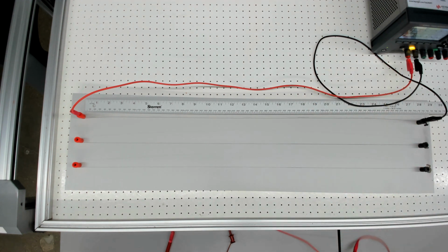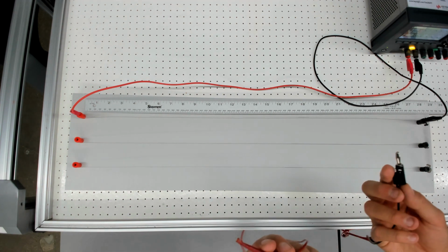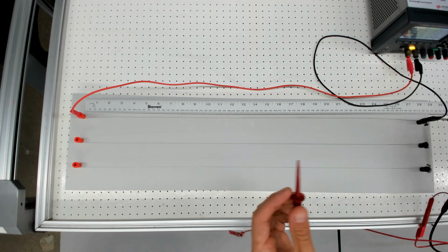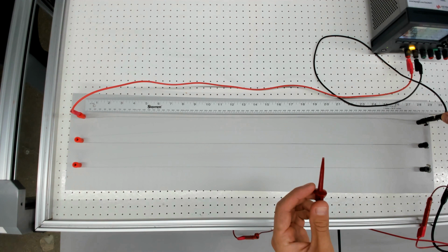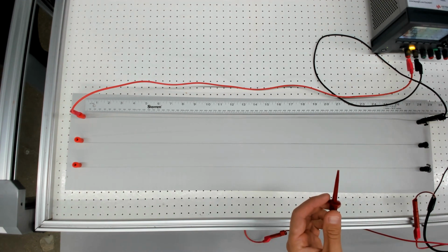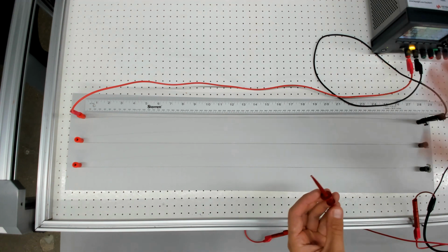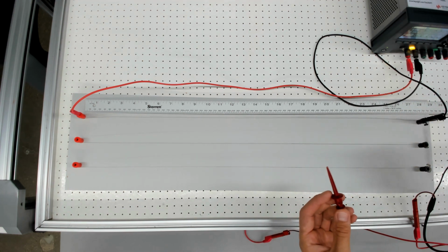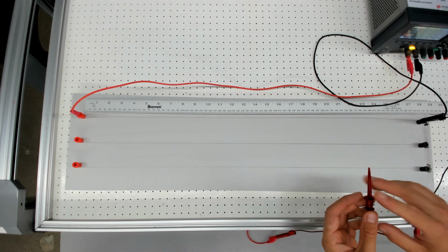The only other change we're going to make to our setup here, in addition to having our meter stick up here, is we're going to take our 2 cables that we have coming from the DAC and hook them up here. So we're going to start with our black cable tied to the black coming out of the power supply. So we're just saying that 0 is the same across the DAC and the power supply. We're tying our grounds together.